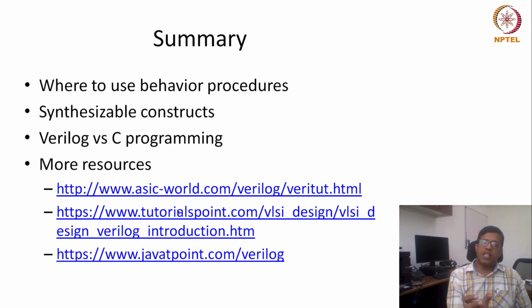This reg type can hold two different values, one is the current value, another could be the future value, while a wire cannot have two different values, so the previous value will get erased. So that's why it's good to use the behavior model when modeling sequential circuits.